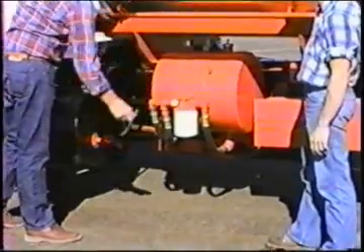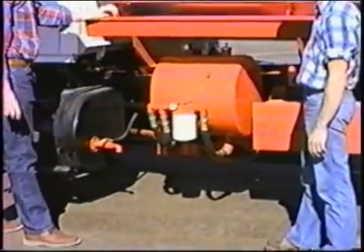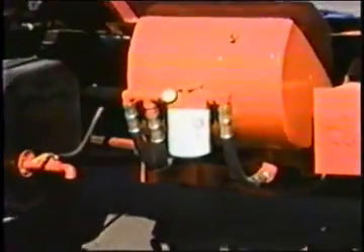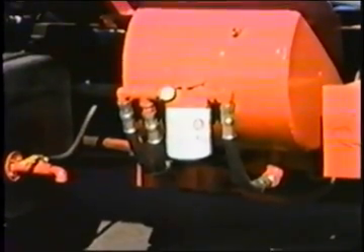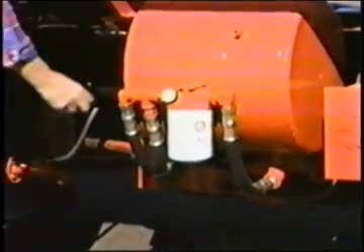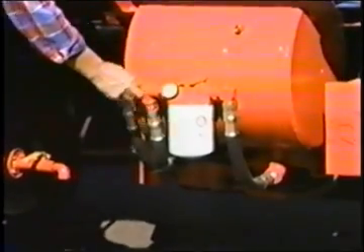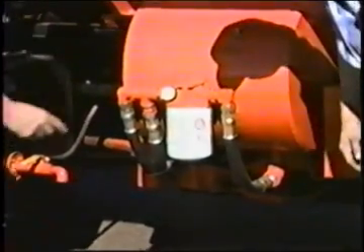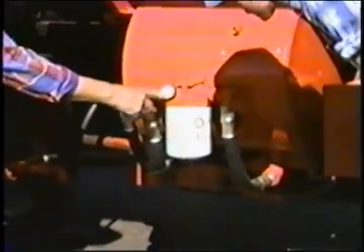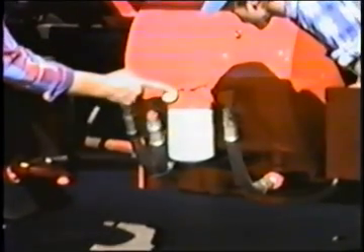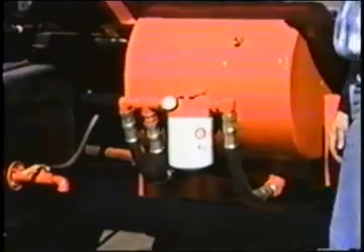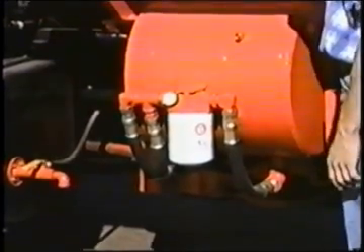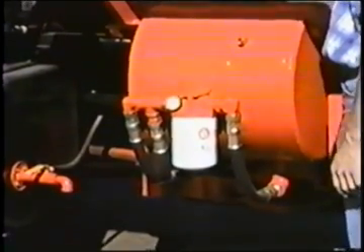Hydraulic filter, this is the filter on both hydraulic systems, both the hydrostatic transmission and the auxiliary hydraulic system that raises and lowers the wings. Got a vacuum gauge on it. That vacuum gauge now is down at 0. If it were to get up in the neighborhood of 10, that's 10 inches of mercury, it's time for a new filter.